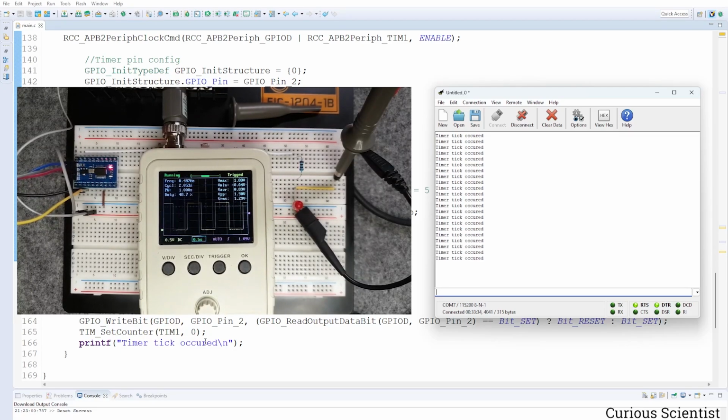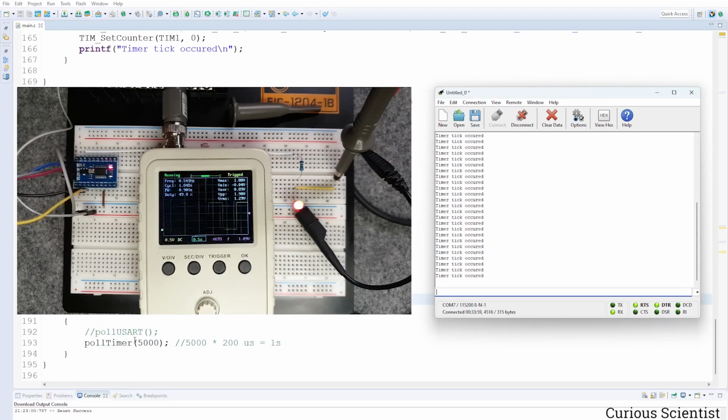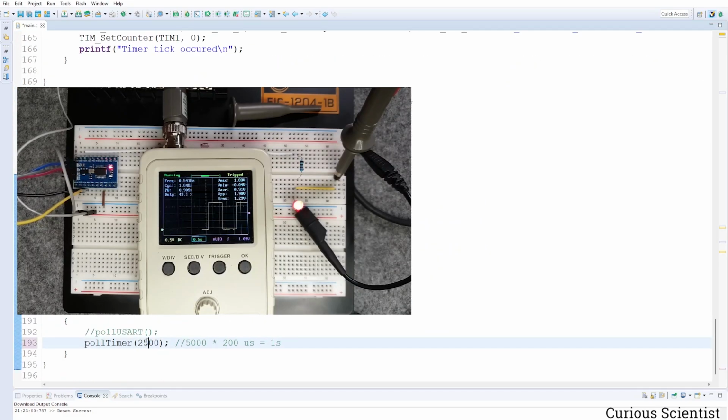And that is exactly because of this toggling that I explained: in the beginning the signal is high for 1 second, and then it's low for another second. And then after 2 seconds it returns to high, completing a full cycle. So the period is actually 2 seconds, and 1/2 is half. So then in order to double the frequency, we need to count only to 2500.